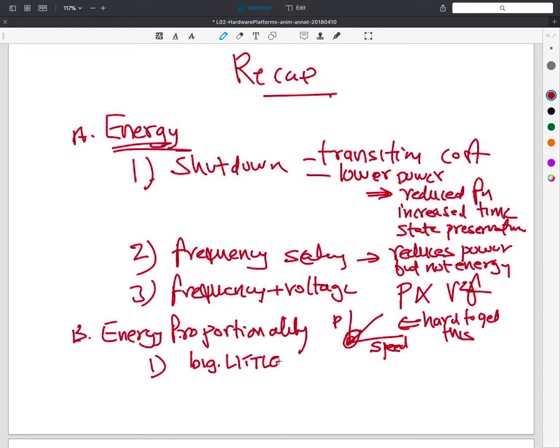But commercially, you will see big.LITTLE very commonly available in processors where they pair up a simple processor and a big processor with identical instruction set architecture. So the same program can run on both places. Their microarchitecture is different, and I've given the example of ARM, because ARM has the same 32-bit instruction set with vastly different implementations out there.